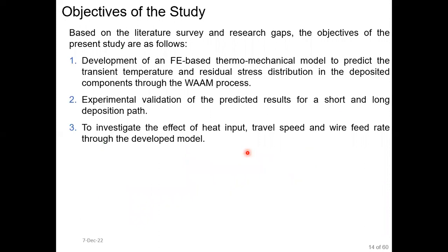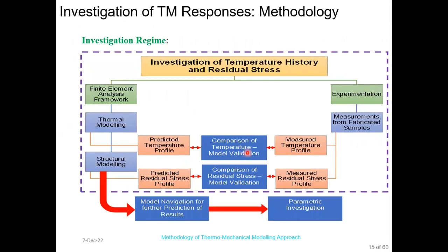So the objective of this study is to first develop an FE-based thermomechanical model which is able to predict the transient temperature and residual stress distribution in the deposited component. After that, real-life experimental validation, and after that, an investigation of different process parameters with the help of the developed model.